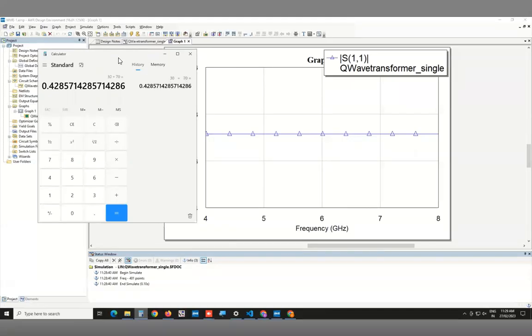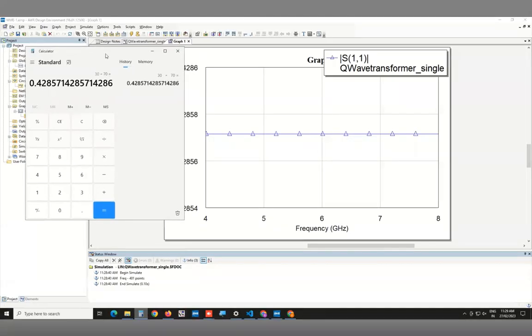So remember, I just told you that when you plot it without the dB, it plots the voltage reflection coefficient magnitude. And Z minus Z naught over Z plus Z naught is the formula for the voltage reflection coefficient. And here there is no phase, because everything is real. The phase is 0, basically. We can even confirm that in a second, but that's what is plotted here.